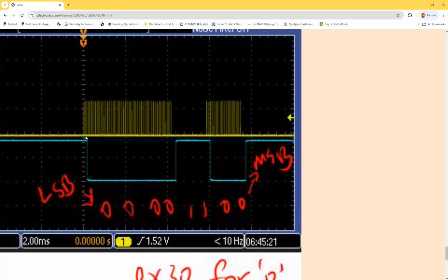BJT, photons, air, receive it, decode it, boom, comes back to the board, receive it. How come the decoder goes low once it receives the signal? I said you can modify the circuit by whatever you want. It's just a pull down, pull up thing. It just matters how the resistors are either connected to ground or to VCC. You can modify the circuit easily. But anyway, whenever you see pulses, it's going to give you a 0. Whenever you send a 0, it's throwing a 1 from the output. We just need to know how that works.